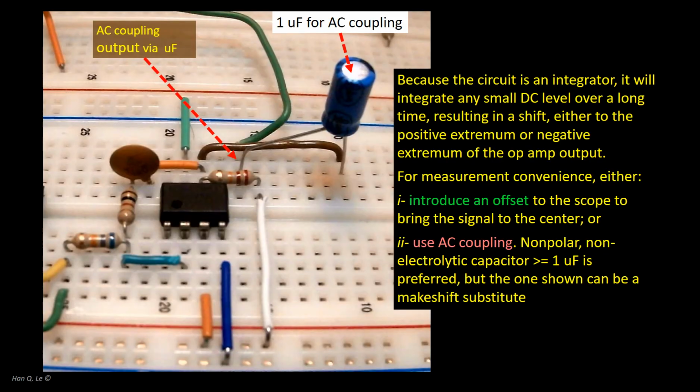In a test at a frequency as low as 10 Hz, although electrolytic type is less desirable than the thin film or ceramic type, a 1 microfarad capacitor was found to work quite well in removing the DC drift while allowing the AC component to pass through indistinguishably intact.